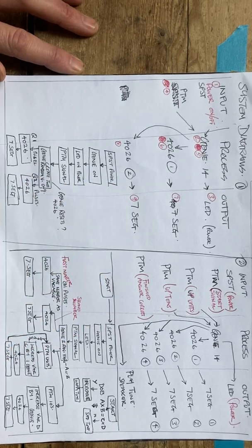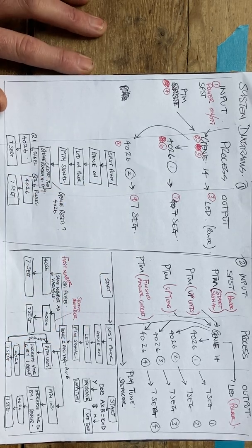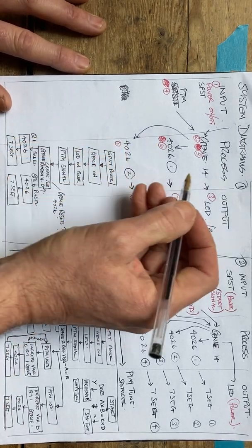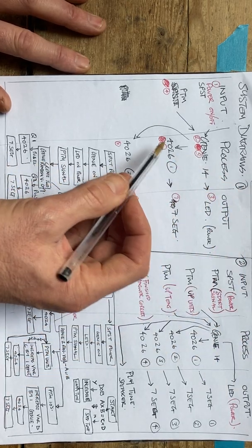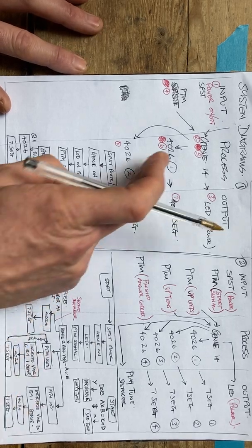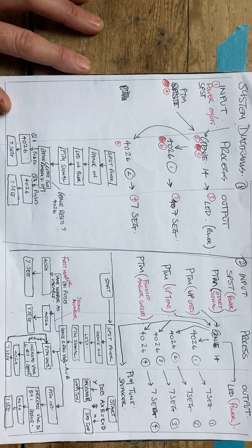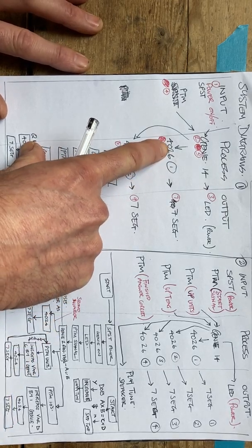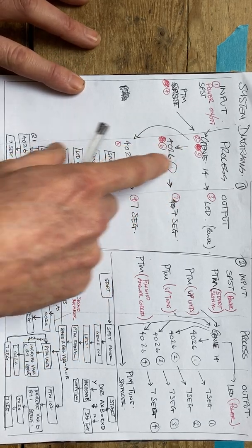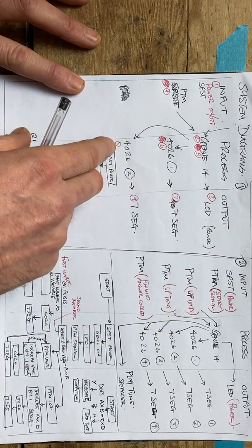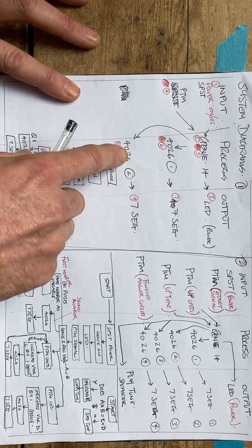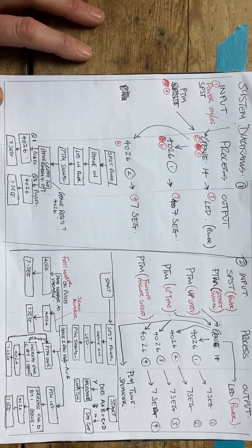It then creates two different random variables. Let's call them A and B. If random variable A is 5, it pulses, let's say Q1, 5 times. Those 5 pulses get interpreted by the 4026, which is a driver for the 7-segment display. So if it pulses 5 times, the configuration on that 7-segment display will show a 5. And we can see how very easily, if the other one is a 7, for example, the other random variable, which will be random variable B, then that 4026 pulses 7 times, and that gets shown on that 7-segment display.